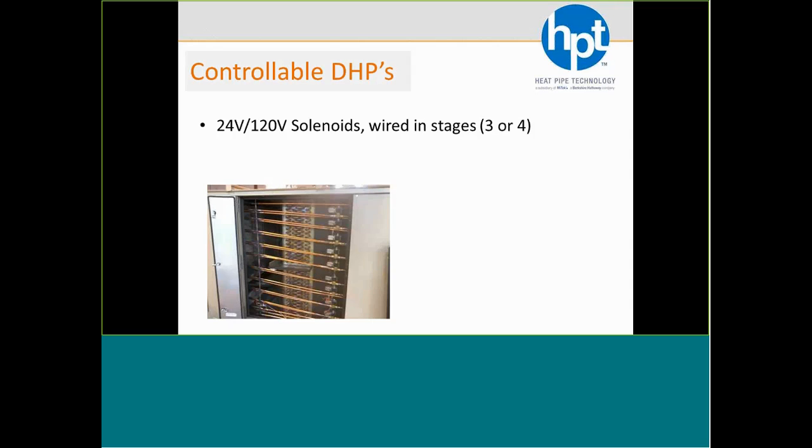So when thinking about that, one question we get sometimes is, what's the wraparound heat pipe doing during heating mode? Is it working against you? The answer is no. When we're in heating mode, first of all, now you've got cold air entering, and that liquid refrigerant is just going to sit at the bottom there, and it's not going to go up anyway. But also, and more importantly, typically that cooling coil is not going to be on during heating mode, and if it's not on, there's no delta T. And without a delta T, we're not going to do anything.